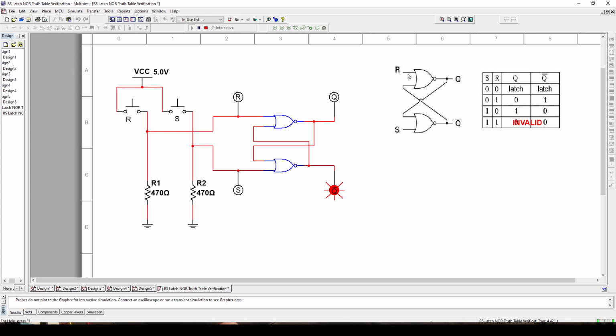If you have one certain condition, you can get a pencil and draw it on a piece of paper, just write the ones and zeros, 0 and 1, and then based on the truth table of a NOR gate, you can come up with the condition of one of them, and then you can follow that into this one, and those two are going to give you that input, and these two, ones and 0, are going to give you the other input.